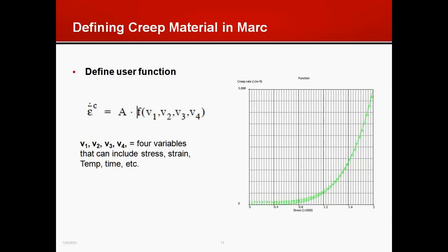And if you have already curve fitted the data, you would have the coefficients that would characterize the material. And we saw one formulation before, which was the power law. But again, as I mentioned, that is not the only one out there. There are very different formulations available for creep, and you may want to use a different equation, which might be better suited for your material.